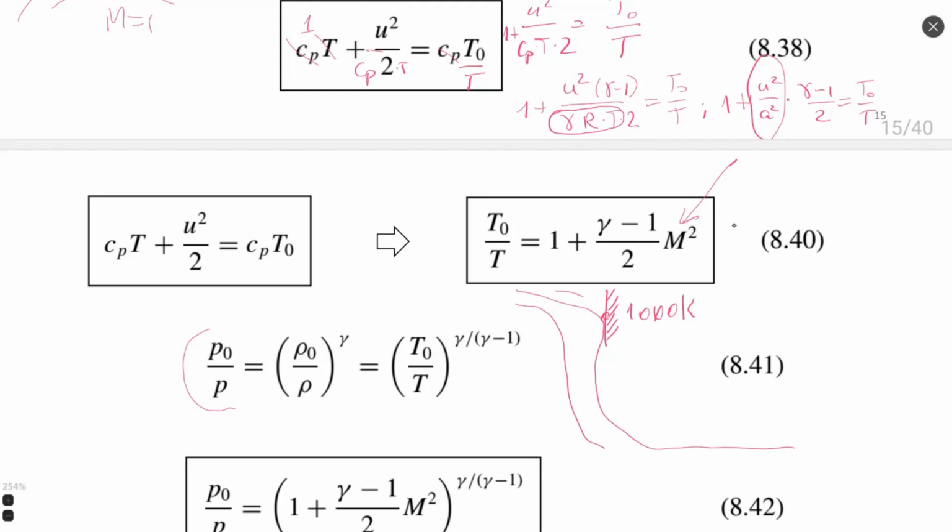At another point, I know that I will have, like in a nozzle, for example, Mach 2. So what does it give me? I put my Mach 2 here, and I put the temperature I measured at the stagnation point here, and I will know my temperature at Mach 2. So the temperature where I will have Mach 2, I will be capable of calculating analytically, without introducing any kind of sensor, just with an analytical method.